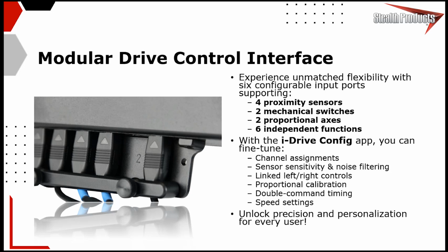And then when you get into it and start using the iDrive config app, we as providers, clinicians, technicians, what have you, can fine tune the performance of those inputs to really match that client's needs and abilities. So we can customize things like joystick settings, like deadband and throw distance.